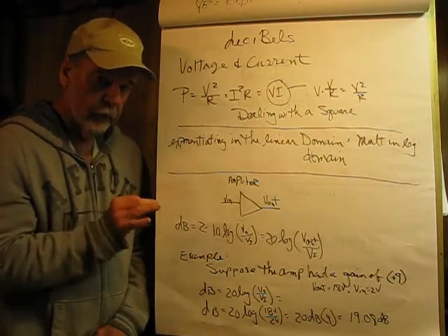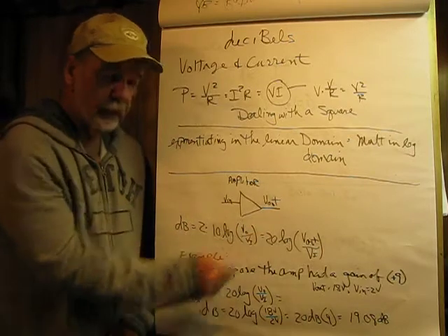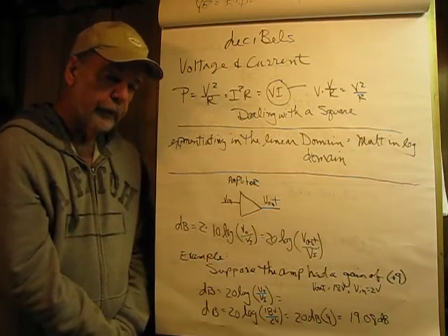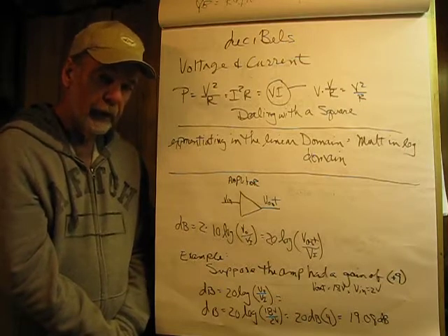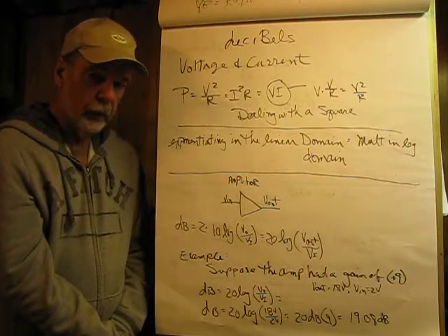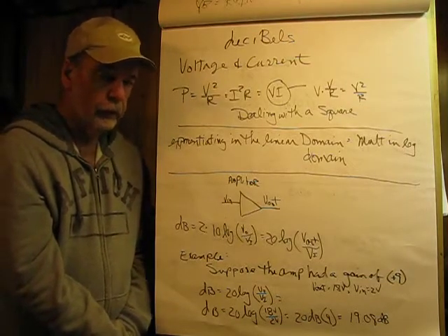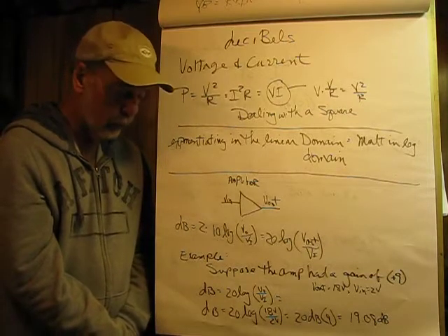It's critically important that you use 20 when you're working with voltage and current, and 10 when you're working with power. If you don't, unless you're dealing with unity gain, your answer is most likely going to be incorrect.